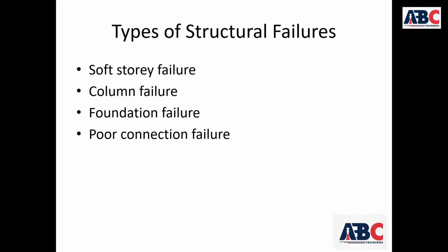This point is column failure. Columns are mostly typical structural elements. If a beam fails, the building may still stand, but if a column fails, the entire structure can collapse. Collapse will occur due to insufficient reinforcement, poor ductility detailing, weak concrete, strong beam, weak column design.